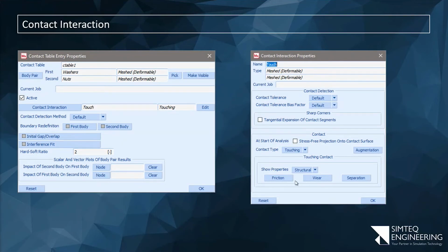So why do we define friction here and not as part of the contact body? Because friction is not a function of a material or a part. Friction is a function of two materials touching. The classic example is Teflon and steel. If I look at steel on steel, the friction coefficient may be something like, for argument's sake, 0.1. If I look at Teflon on Teflon, that's, let's say, 0.01. But Teflon on steel is also the same as Teflon on Teflon, so it's still 0.01. In other words, friction is a function of two materials touching, not just one.